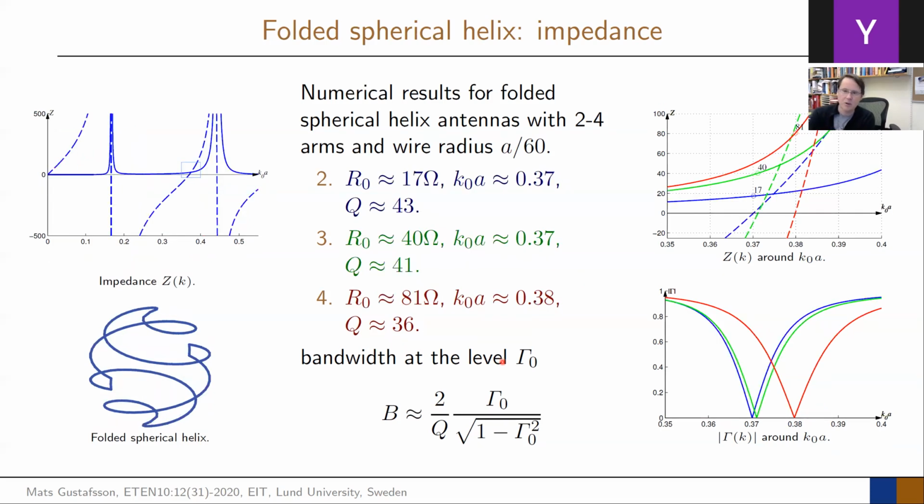And here you can see all of them at once if we compare them. So you can see here, yes, the radiation resonance frequency shifts a little bit, but very, very little. And we can see that the main thing that's happening is that the slope of these lines is changing when I add more lines. That is a dominant effect. And the next thing is that the radiation resistance here is also moving up higher. Those two effects come in.